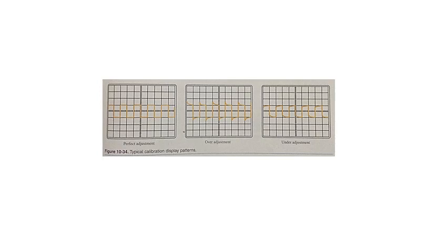Intensity and focus. The focus and intensity control the appearance of the wave on the CRT screen. Focus is used to make the wave appear sharper. It eliminates any fuzzy appearance the wave may have. The intensity controls the brightness of the light beam striking the front of the screen. The intensity should never be set at a level higher than is needed to comfortably observe the wave pattern.